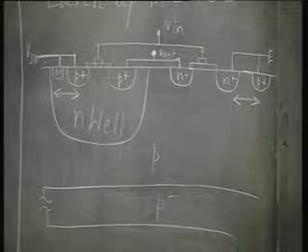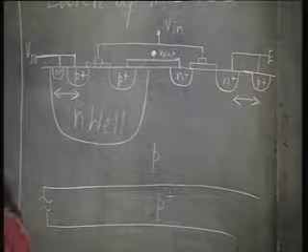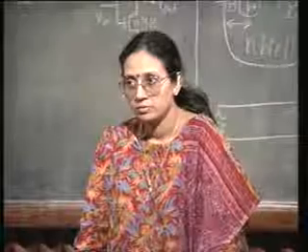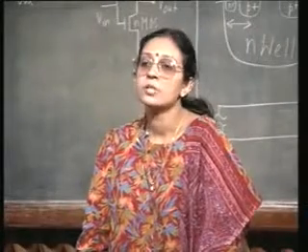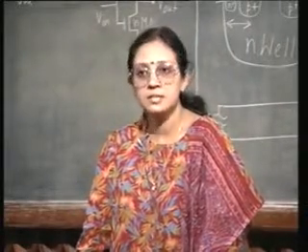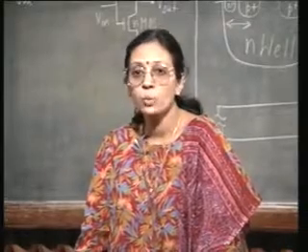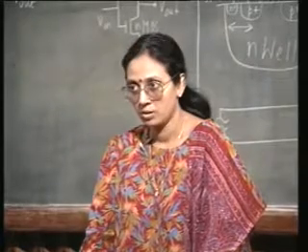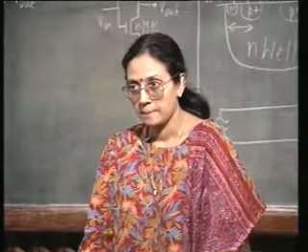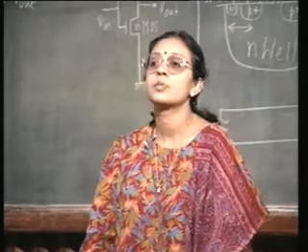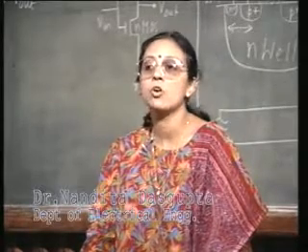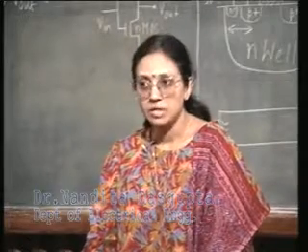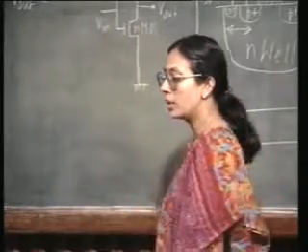So, you may have an initial fluctuation, but it is not going to get latched up, because you have drastically reduced the resistance in the path of the current without sacrificing your MOSFET performance at all. Of course, you have increased the process complexity, you have increased the cost of the process by using an epitaxial wafer instead of using a bulk wafer.